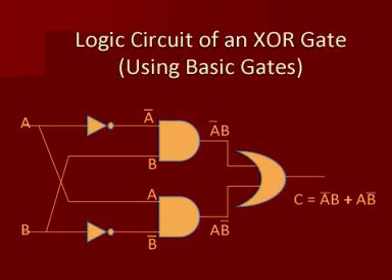While designing a logic circuit for the Boolean expression derived earlier, the following steps are taken. We place product terms in the Boolean expression with AND operation with the appropriate inputs. Wherever we have a complemented term in the Boolean expression, we use a NOT gate to invert that particular input before ANDing it. We then OR all the outputs of the AND gates to perform the summing operation in the Boolean expression.